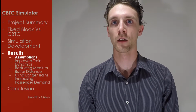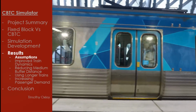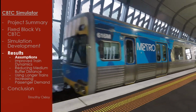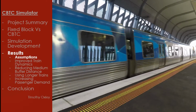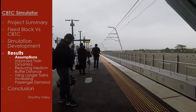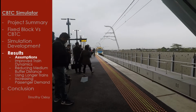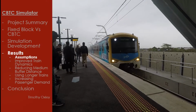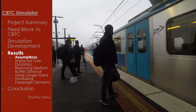Results. Due to the relationship that exists between the number of passengers boarding each train and the extent of delays incurred, it can be immediately justified that it is desirable to maintain the shortest possible headways between trains stopping at platforms, especially during peak demand. This is because a platform that is vacant for a longer period will accumulate more passengers, which will increase delays to the train when it arrives. The increased delay will lengthen the period that passengers can accumulate at the next platform, resulting in a snowballing effect until the train is fully loaded.